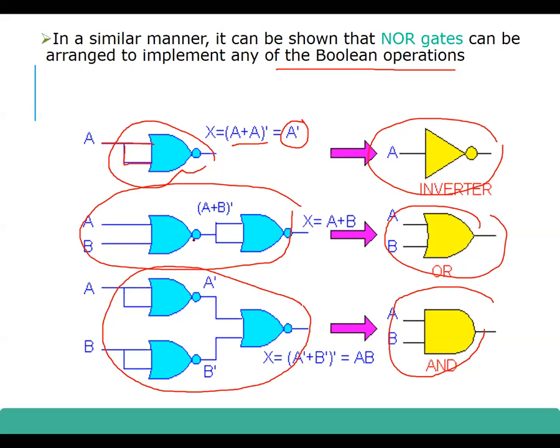You get the NOR of A and B, which is (A+B)', because it is a NOR gate. After that we input it to both inputs of the second gate, so at the end we get A OR B as the output. You get the complement of this input, which corresponds to the OR gate output.